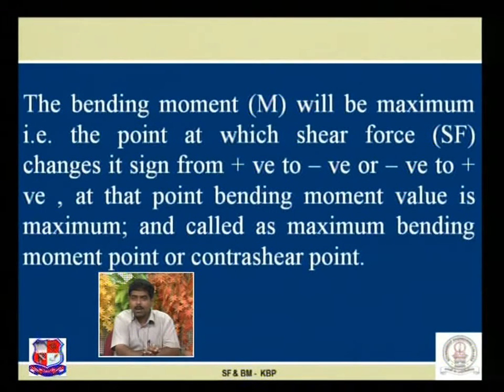Please don't confuse the two terms, point of contraflexure and contra shear point. Let us revise. What is a contra shear point? A contra shear point is a point at which the shear force changes its sign from positive to negative or negative to positive, while a point of contraflexure is the point at which the bending moment changes its sign from positive to negative or negative to positive.